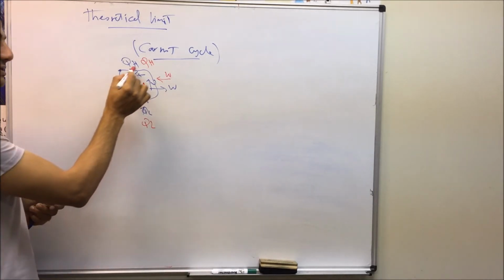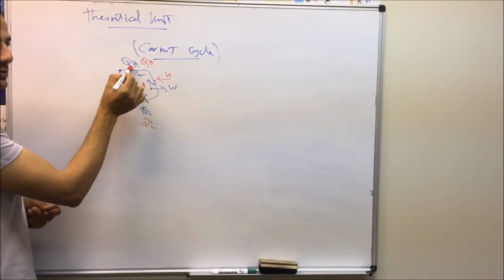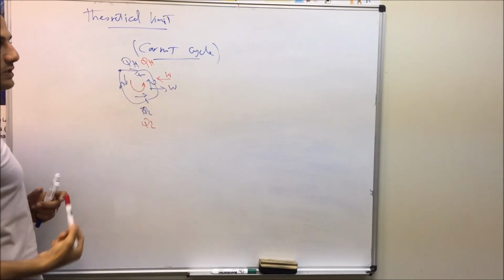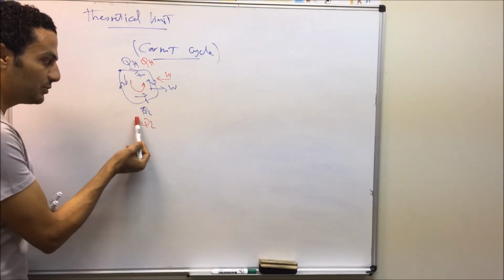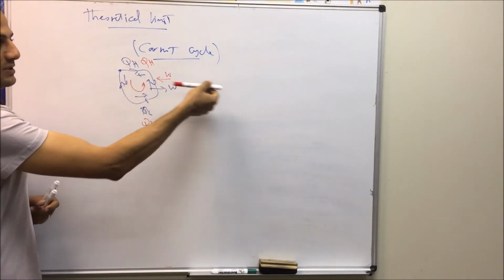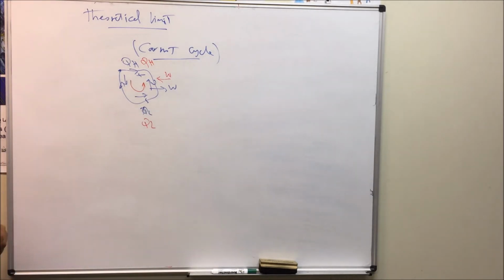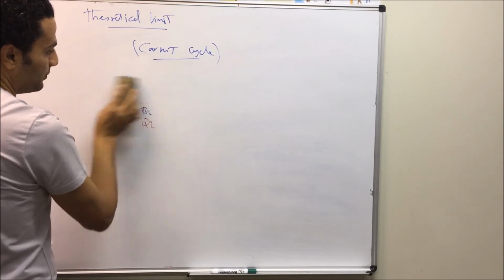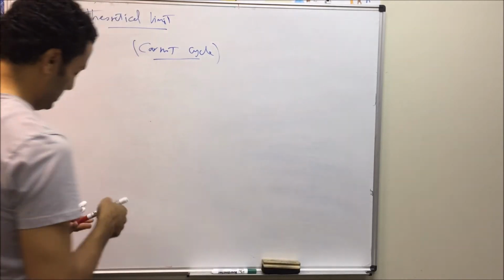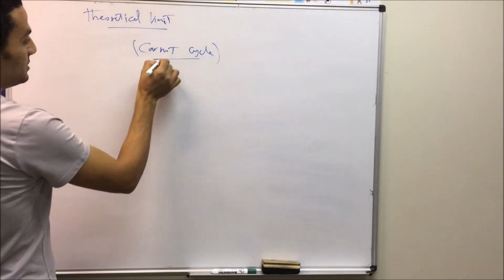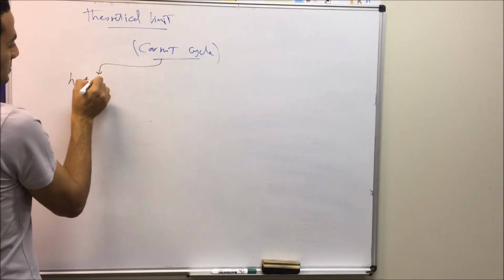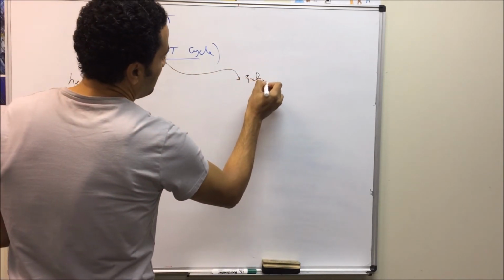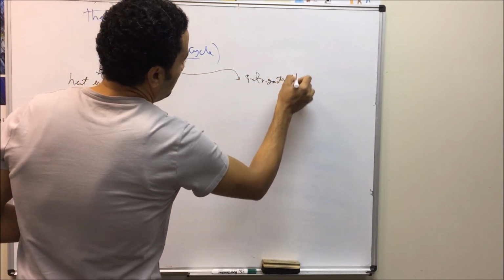As all of the processes within the Carnot cycle are reversible, either we can go in the direction from Q high to Q low so that we can get work in case of a heat engine, or we can do the reverse, proceeding from Q low to Q high, but in this case we have to add input work. So the Carnot cycle, as it is reversible, can be applied for a heat engine, and also for a refrigerator and heat pump.